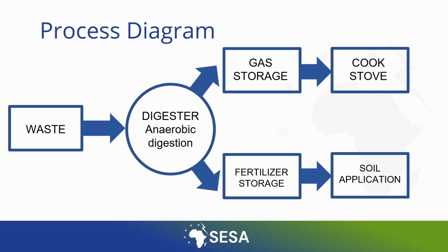This is a generic process diagram for anaerobic digestion. Organic waste is introduced into an anaerobic digester. Within this digester, and due to the action of a series of bacterial families, the degradation of the input organic matter occurs. In this device, it's important to control the temperature and agitation of the digester, so we will achieve an ideal bacteria balance and therefore a good gas production.